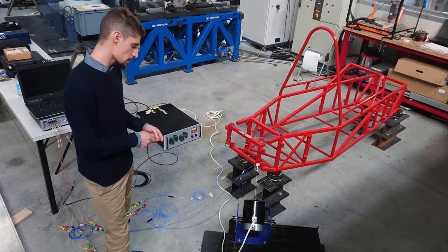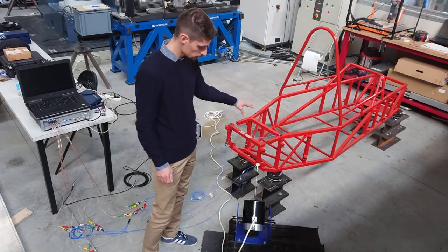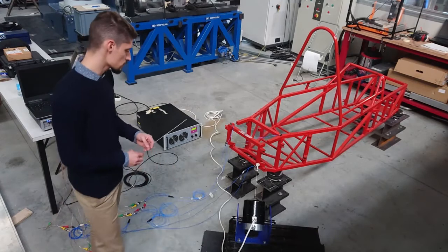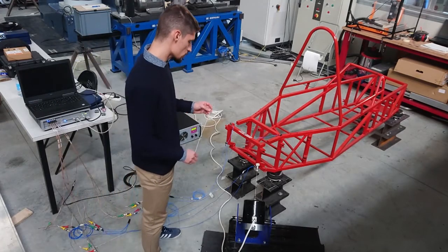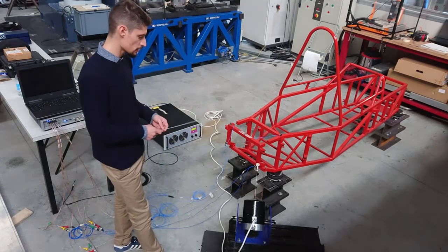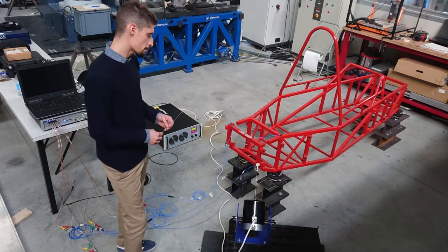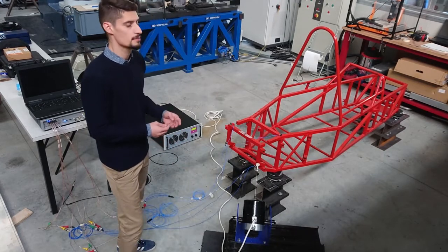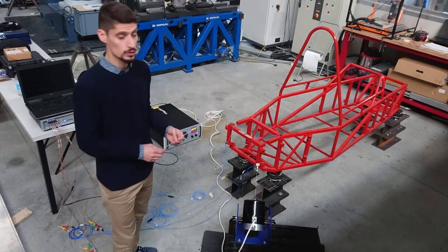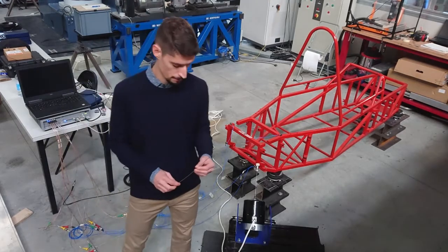that your shakers, so the inputs into your structure, are decorrelated during the analysis, because if during the analysis your shakers turn out to be correlated at some frequencies, you could not estimate the correct FRF, and you would probably obtain false mode shapes and make big mistakes.